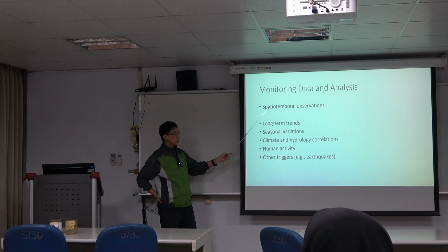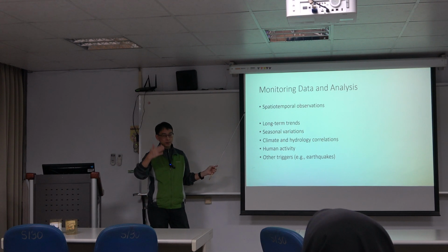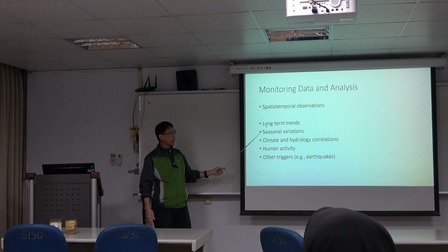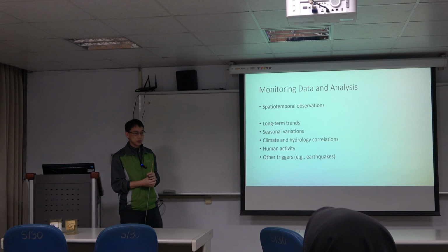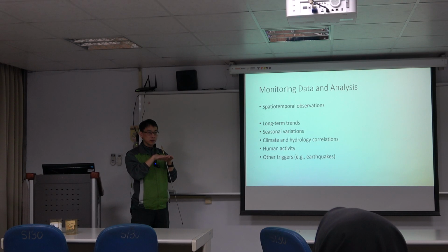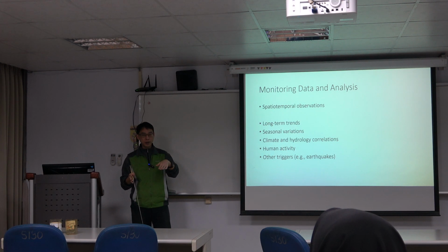And after you have the observations, water level is one of the points. Another could be your chemical compositions. They might have seasonal variation, or they might have a long-term trend. Like for groundwater management issues, we commonly need to see if the water level trend is declining or uplifting. They have seasonal variation, I think there's no problem. But after the seasonal variation, you might be able to see whether the trend is a decline or an uplift. For example, if you would like to assess the water resources, a continuous decline might induce depression problems. You might not be able to have sustainable management.